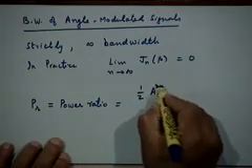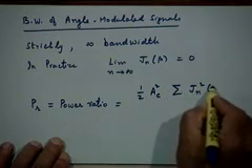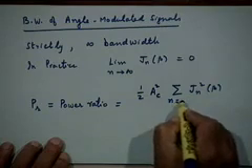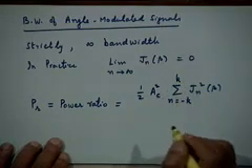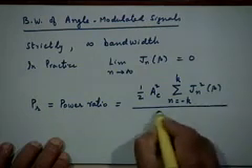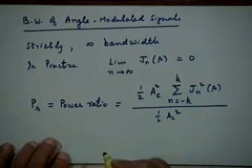It will be half A_C squared times the sum of J_n squared of β, n going from minus k to plus k, and the total power is half A_C squared.